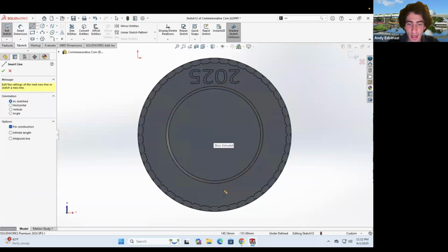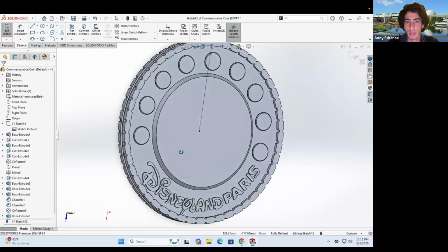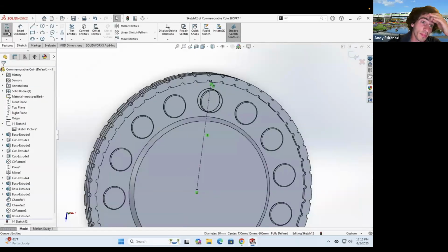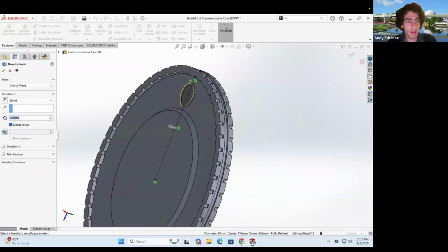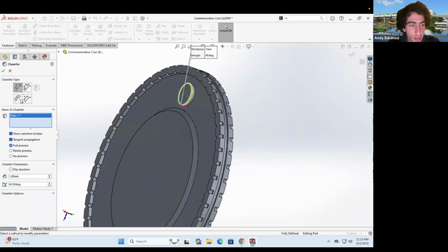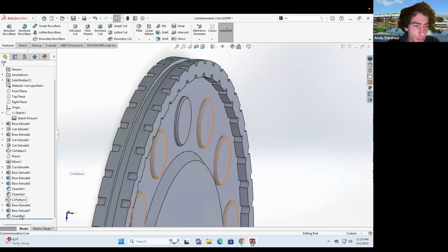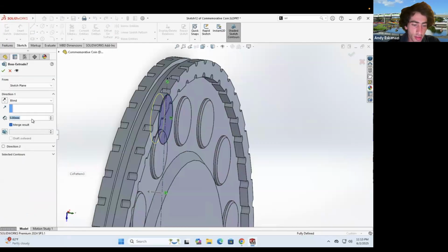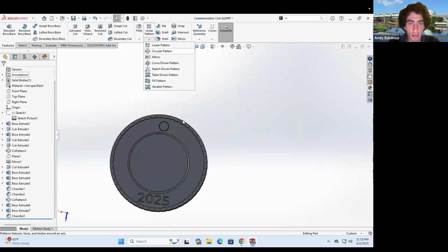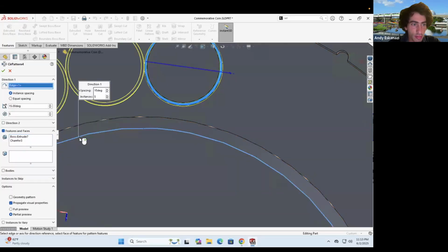And then we are going to, there we go. Excellent. Actually, I could just convert entities. That guy right there, extrude by 5 millimeters. Then let's do our chamfer right there by 1. Good. 5, or was it? No, it was 2. I'm going to come back here, edit, perfectly. Okay. And now we can do our circular pattern where we choose the chamfer like that, this direction.